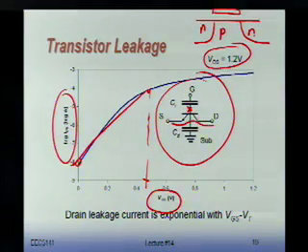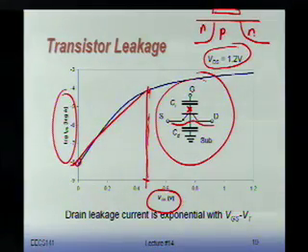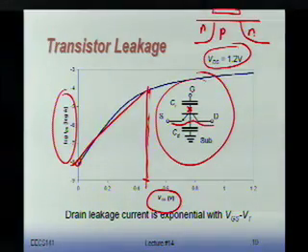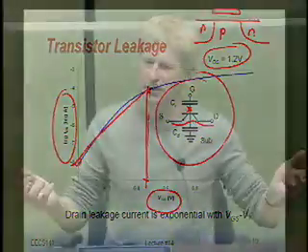Well, it's the following thing. In the good old days, we were operating at VDD of 5 volt, and people were happily operating with threshold voltage of around a volt. But nowadays, for energy purposes, and also because of electrical fields, you make things smaller and smaller, so I have to scale supply voltage. If I scale supply voltage and I don't scale threshold voltage, what do you get?